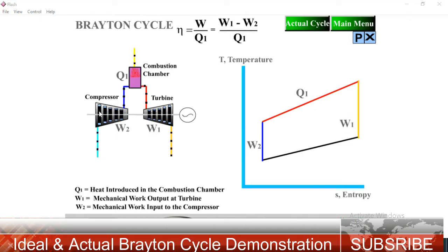The air standard Brayton cycle represents the states visited by the gas turbine, with additional heat exchangers so the air releases heat to the surroundings and returns to its original state 1. The air standard Brayton cycle consists of two heat exchangers, a compressor and a turbine.